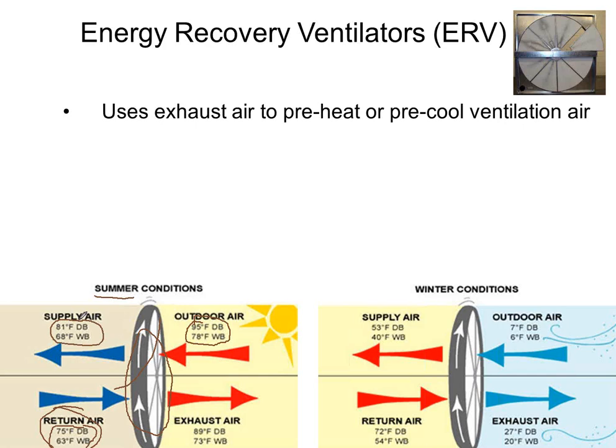So that's usually one of my targets when I'm sizing an ERV, is to get things to 80-67, and I know the rooftop or the air handler or the fan coil or whatever will be able to handle it from there without any problem. And that's nice, and I get some free cooling benefit here in the summer and definitely some dehumidification benefit, which is really nice.